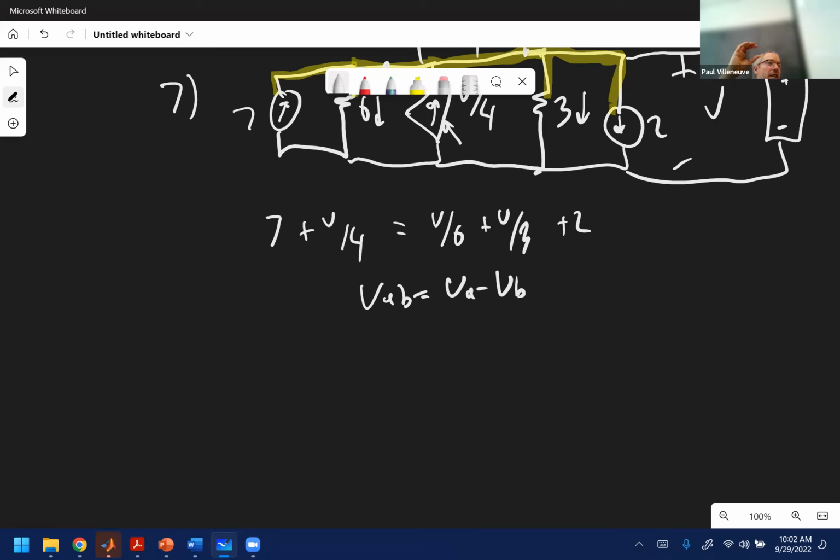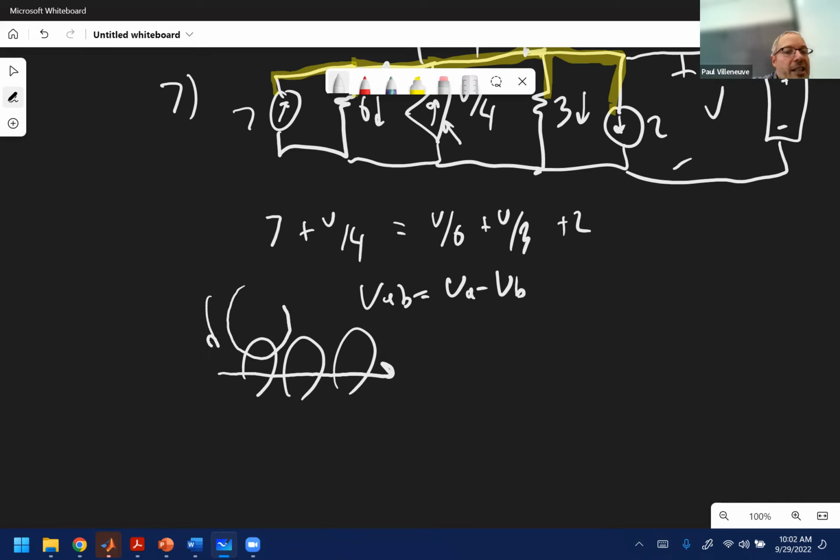Yeah, so if you have clamp-ons, you actually work for DC. It used to be only for AC, but now they have what are called Hall effect type ones. Because what you're doing is whenever you have a current, and we'll learn more about this if you take 321 with me, whenever you have a current carrying wire, you have magnetic fields that emanate outside of that. So if I can put another device that can loop around and see that magnetic field, that's going to induce a current, and then I can measure a voltage there.